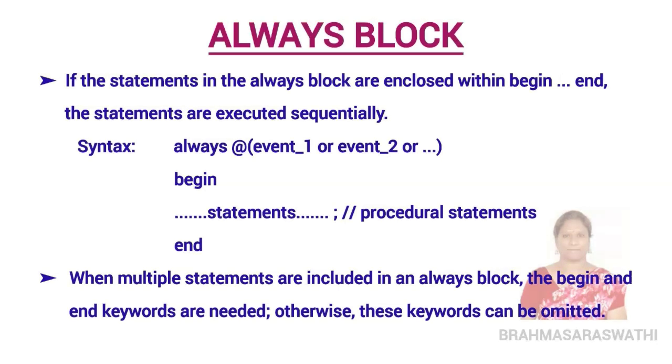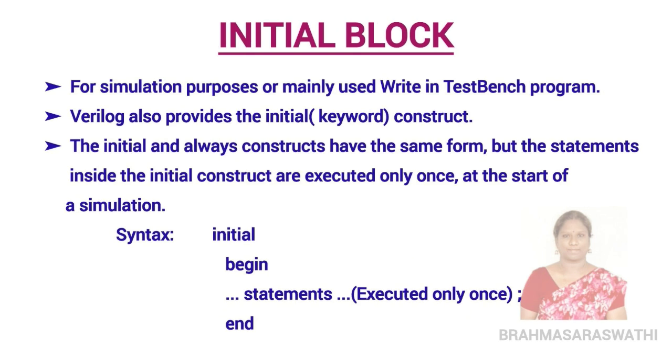The next point is when multiple statements are included in an always block, the begin and end keywords are needed. Otherwise, these keywords can be omitted. This means if you want to write more than one statement in an always block, begin and end are compulsory keywords. Between begin and end, the statements are written. If there is only a single statement in the always block, there is no need to write the begin and end keywords. We can neglect them. The next topic is the initial block.